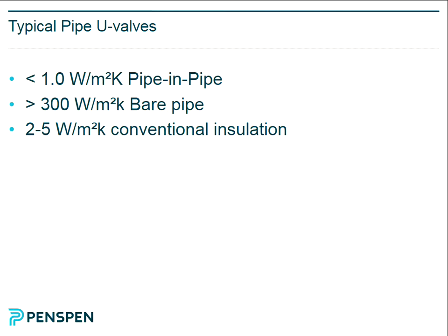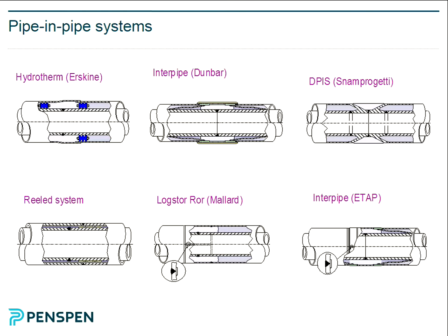So these are used for insulation systems for cryogenic pipelines like LNG, and for downhole typically. And Interpipe do use vacuum insulation sometimes as well for their pipe-in-pipe system. So vacuum is one good way. Bundles we talked about, hot water flushing going through them.